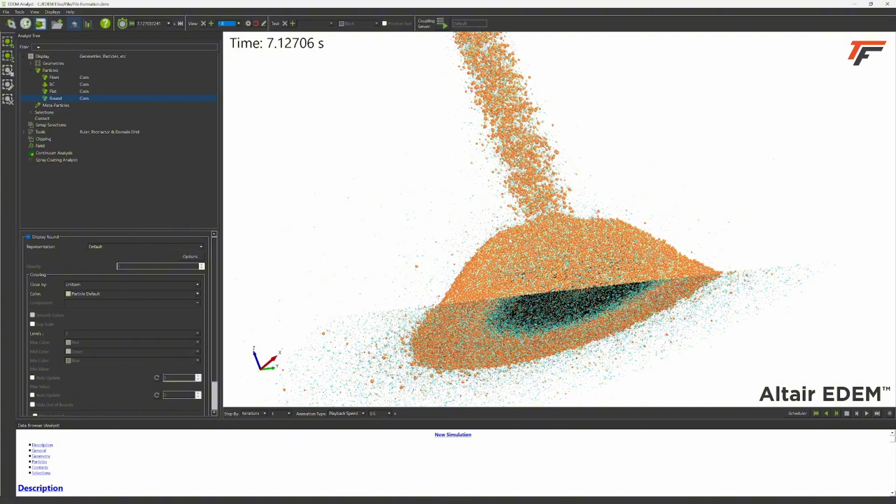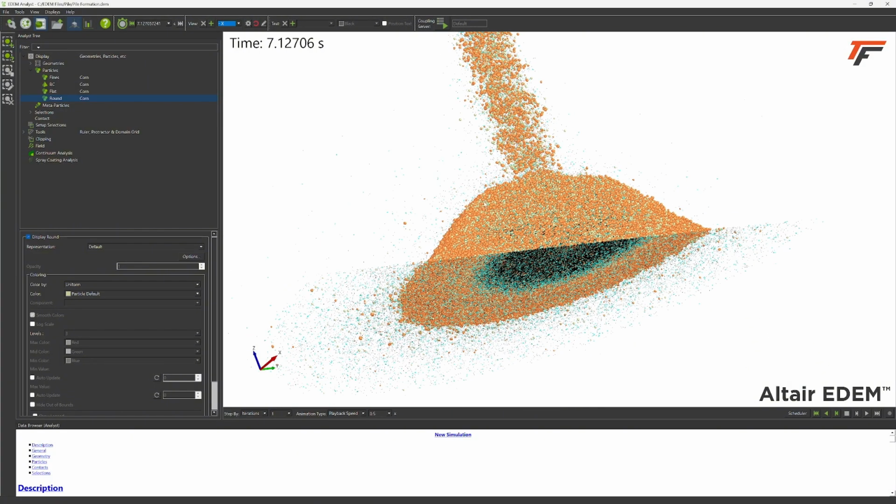And that is going to create a couple issues. Number one, you're going to have a lot harder time unloading. This section of the bin is not going to unload as easily because you're going to have sticking, heat. It's going to be more densely packed because of all these fines being present in here. You're also going to have your initial loads be higher in BCFM. That's broken corn foreign material. And that BCFM, on larger bins, will a lot of times represent some dockage on some of your initial loads.